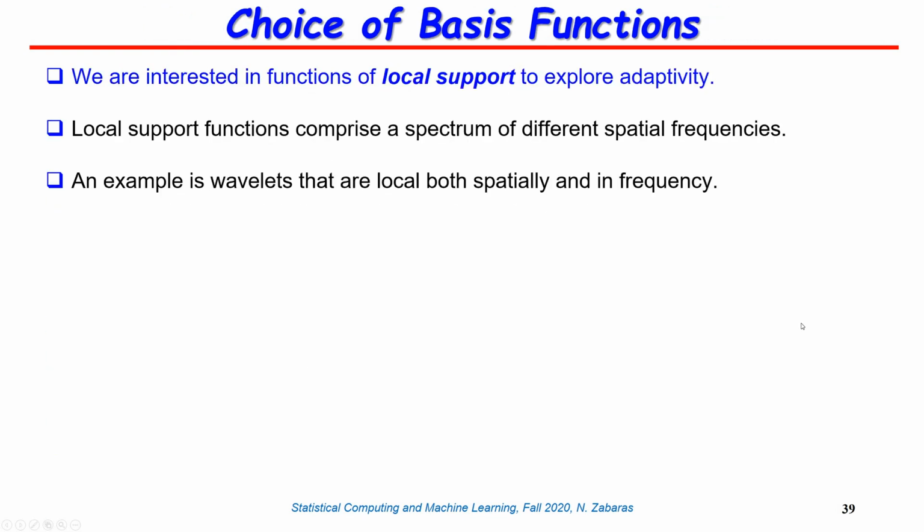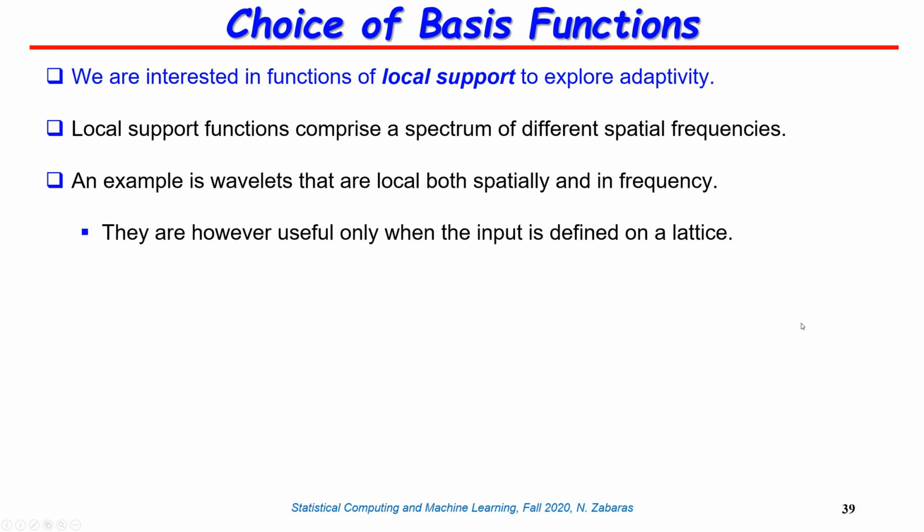Okay, one of the things that I will insist you pay attention to is that it makes sense for these basis functions to have local support. And what I mean by that, remember, wi multiplies the basis function phi i of x. So you don't really want, when wi changes a little bit, to affect the solution everywhere. You only want it to be affected in the support region of phi i of x. So we would like these basis functions to have local support.